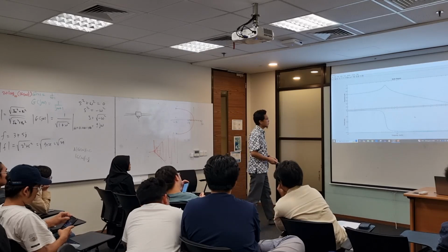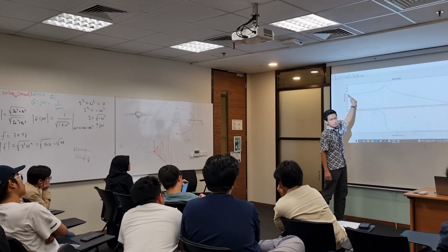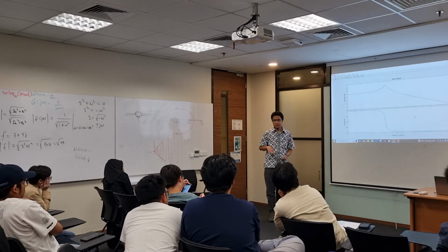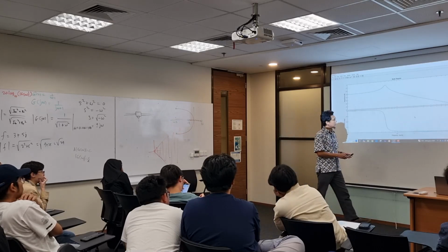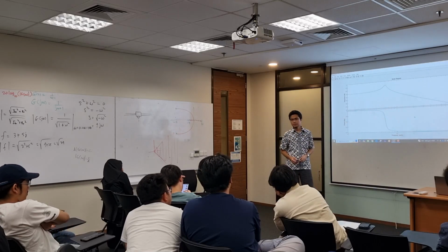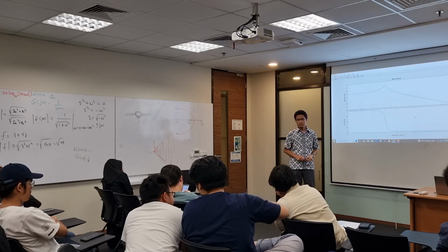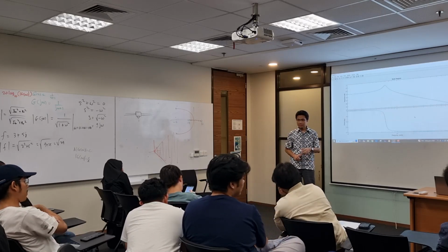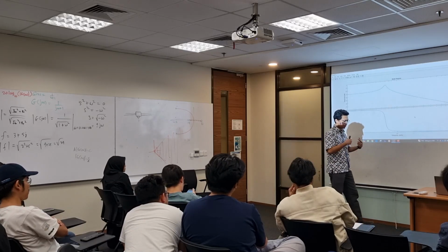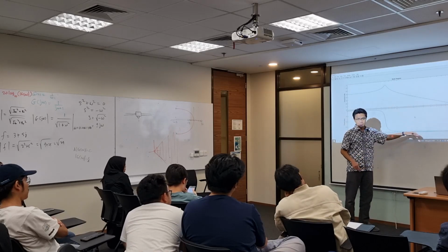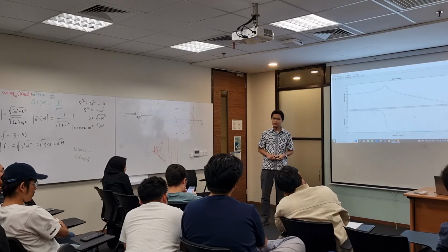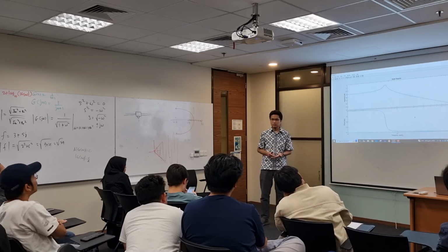So it is not always using the system in this region. You know the car suspension? The car suspension is working in this region, not in this region. Because when a car is moving very fast, the input frequency to the car suspension is very high compared to the suspension natural frequency. Suspension natural frequency ranges from 1 Hz to 2 Hz for a passenger car.